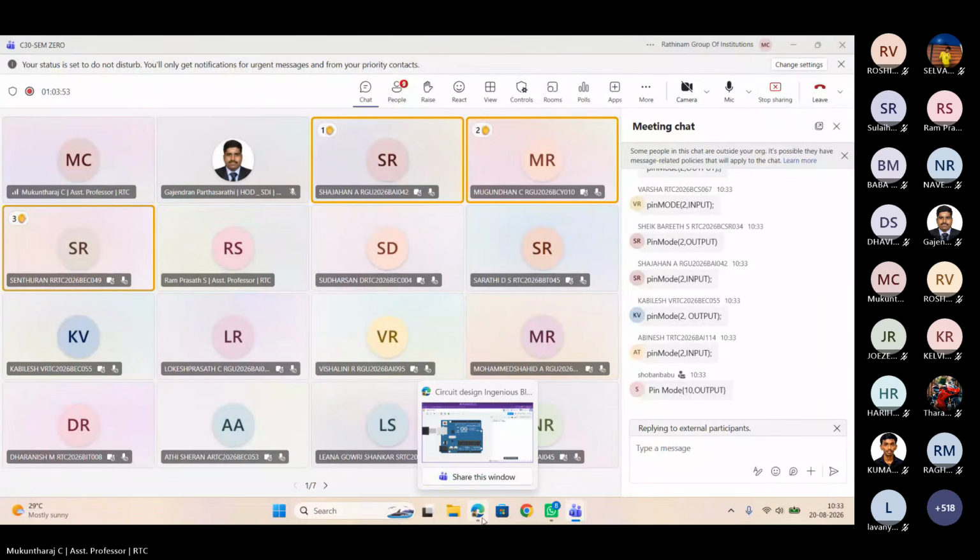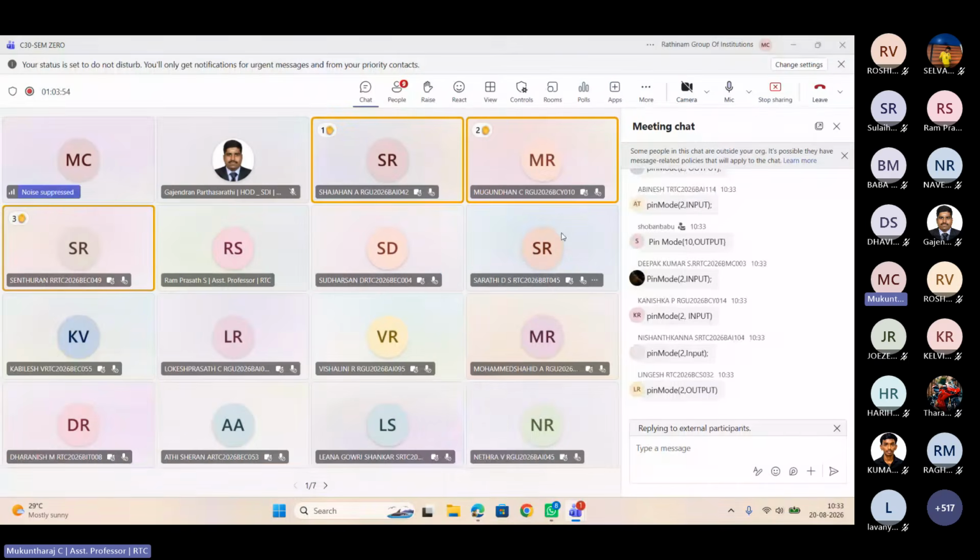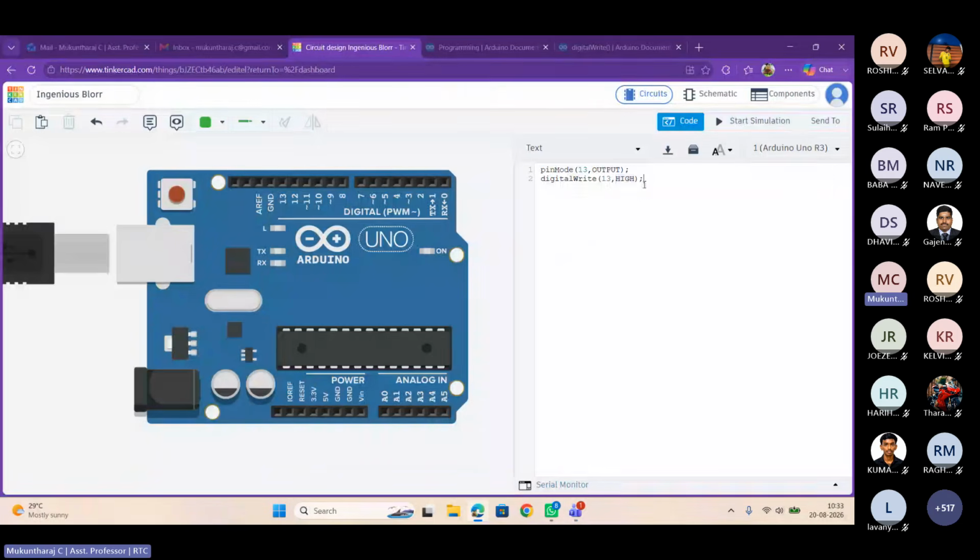Okay. So coming to digital write. Simply we made one pin as output pin, correct? Output in the sense the controller is going to provide certain value to the pin. So for making the LED to glow, I want to make that particular pin high. You can make a note of it. If I want to make the LED to glow, I want to make that respective pin high. This is on one condition that yesterday you people may have heard of.